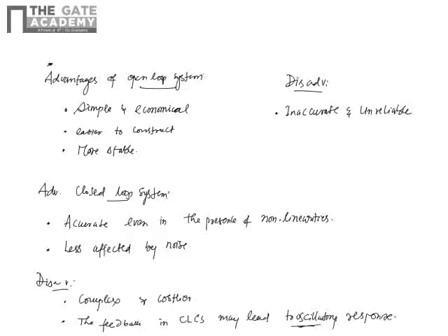That means there are two types of feedback. If I use positive feedback, the system may oscillate. If I use negative feedback, it is more advantageous. Even though the gain may reduce, the bandwidth will increase. That's the advantage of negative feedback.